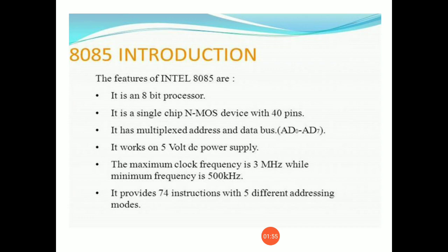This microprocessor provides 8-bit input output addresses to access, so there are 2 to the power 8 or 256 input output ports.